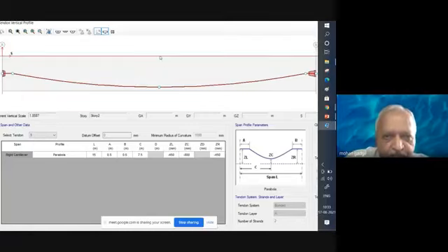Okay. Now from this line, I am measuring downward the distance, which I have defined as minus 800. You can see that 800. So at the center, this node that I have considered is 800 mm from the top, and it has therefore from the bottom a distance equal to 100 mm. Now that is the center of that cable. So this is the center of the cable that I have considered.